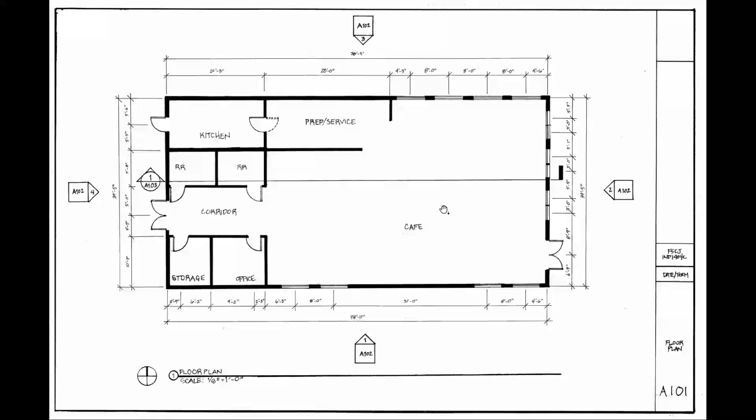We never really want to slice through things like partial walls, or reveal stuff that's cut through structure in this way without showing it, and you'll see what I mean in a second. But for right now, if it skims right up against your furniture arrangement, don't worry about that. We're not going to show what it looks like if you were cut through that little piece of wall. We're just going to show what you would see if you took just a half a step forward.